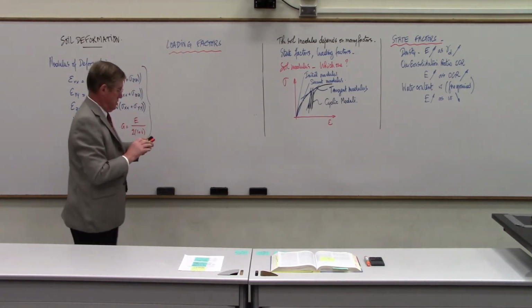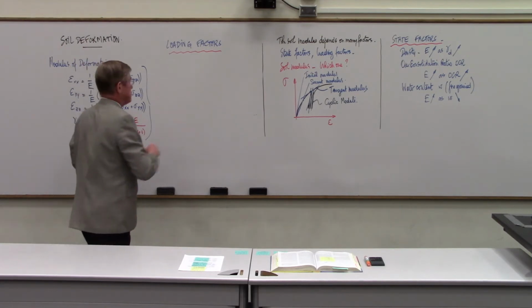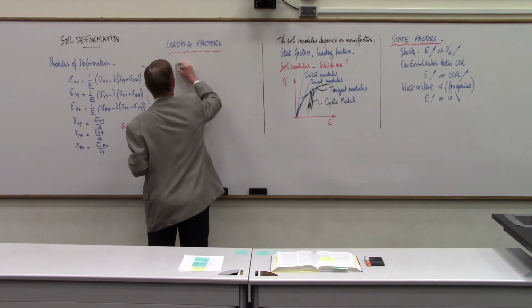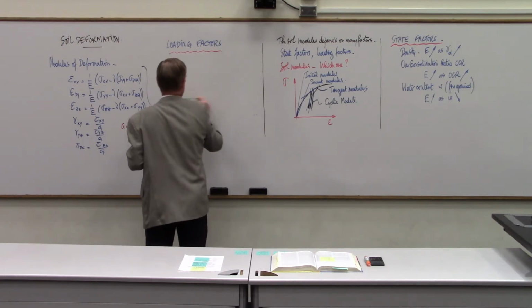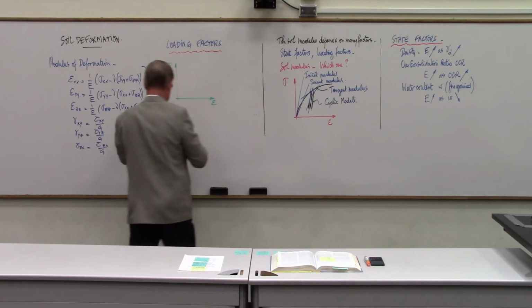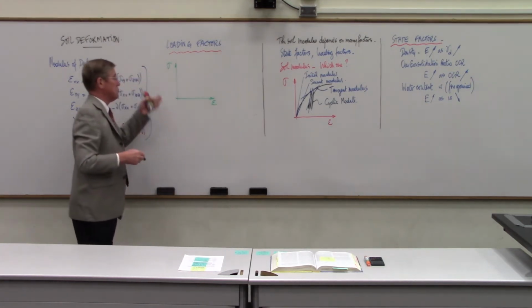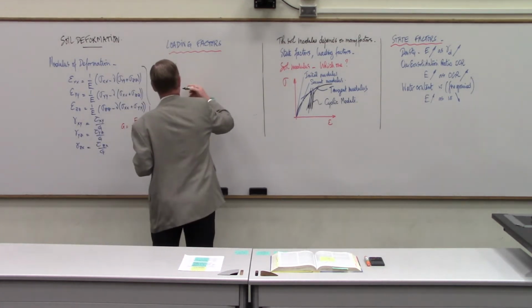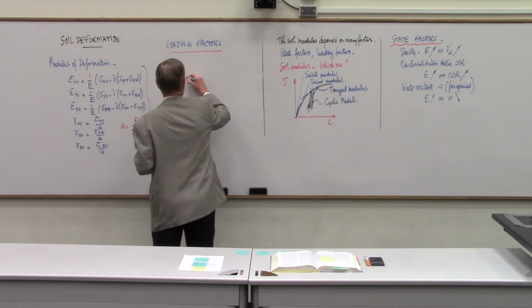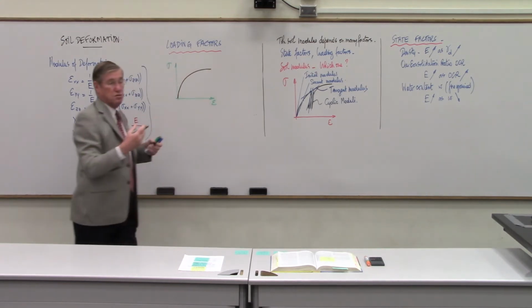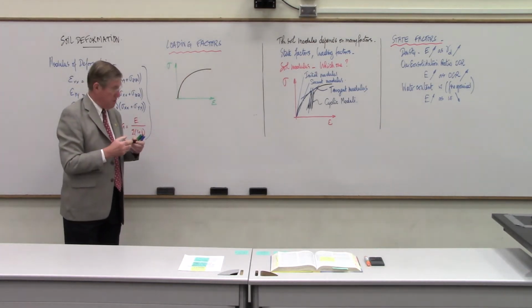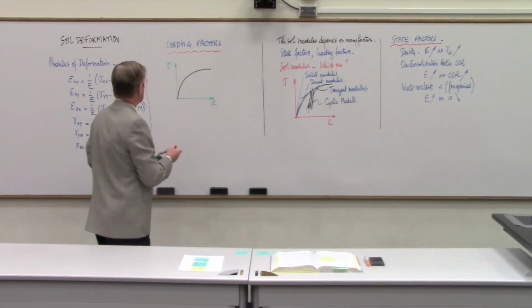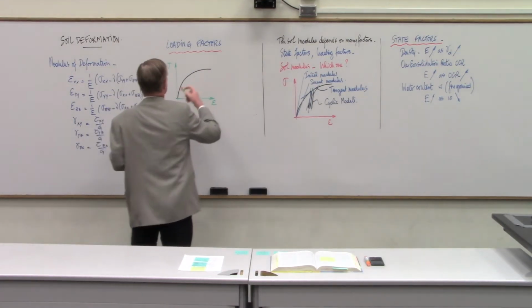Well, first of all, if I draw a stress-strain curve like I've done here, and I put sigma versus epsilon, that could be a simple shear test, triaxial test, whatever. And in here, I have the stress-strain curve. And this being soil, that stress-strain curve is highly nonlinear. The first influence factor that I want to acknowledge is the strain level.